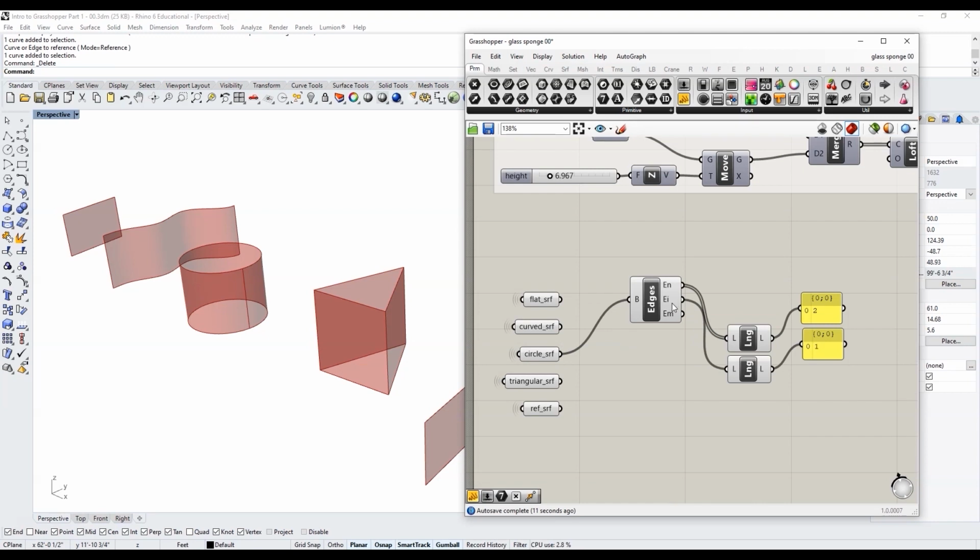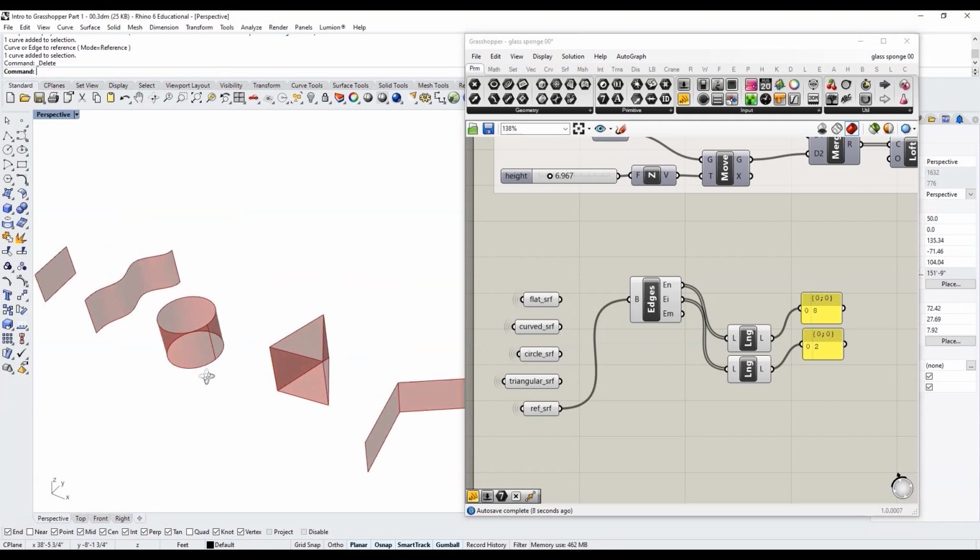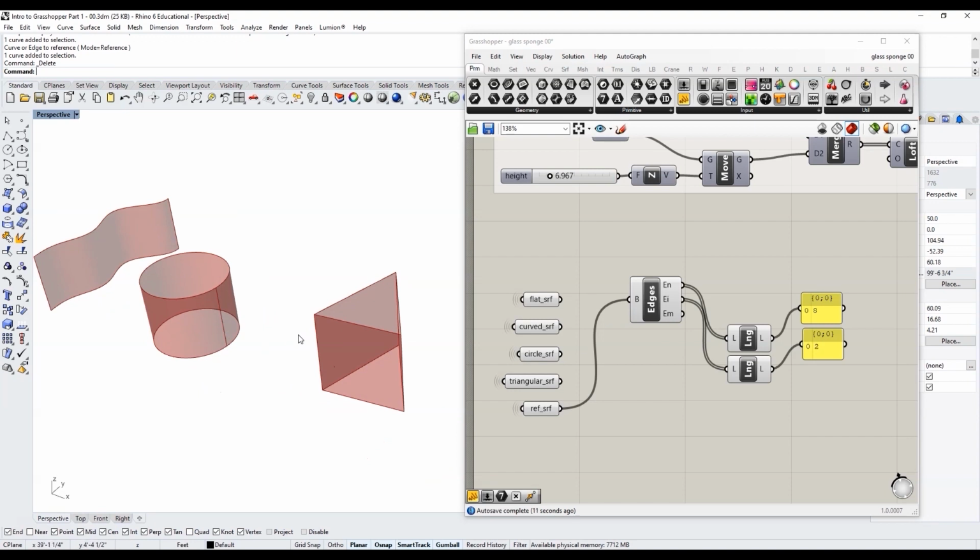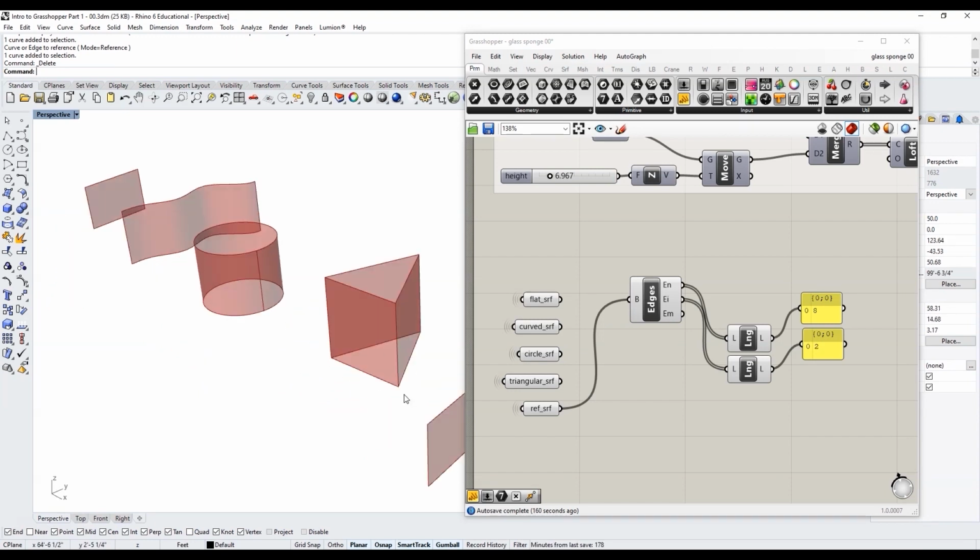And so if we do a ratio here between interior edges and naked edges, it's always going to be 0.5. So 1 divided by 2 is 0.5. And for our triangle, we have 3 divided by 6 is 0.5. That's not the case with our open ones. So 0 divided by 4 is 0. It's not 0.5. If we get our referenced one, 2 divided by 8 is 0.25. It's not 0.5. So that's where the difference is. And if you take the time to think about this, it makes sense for the kinds of surfaces we made.